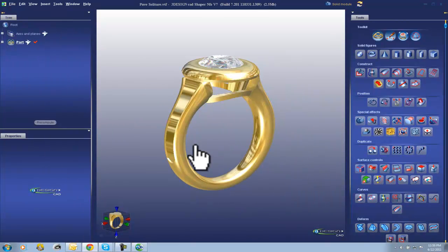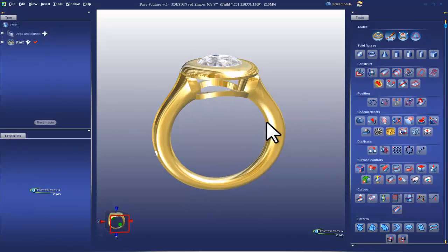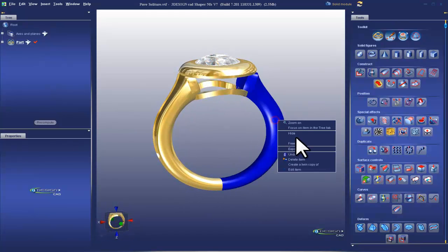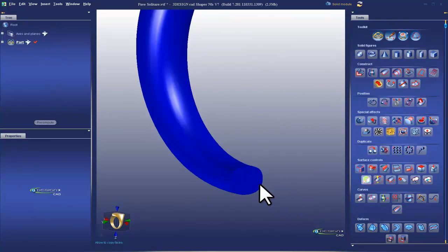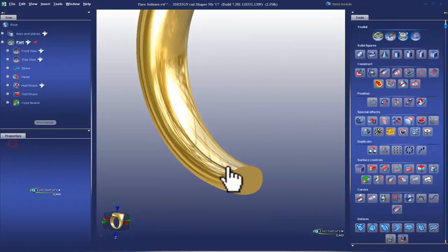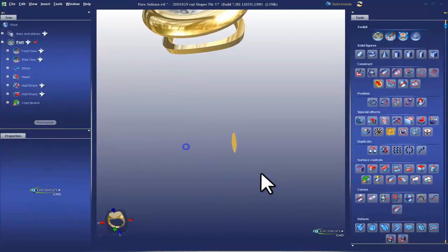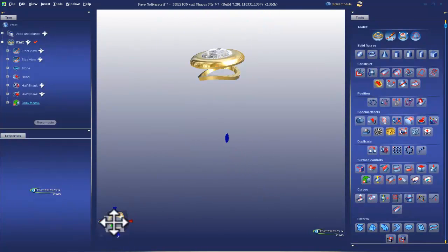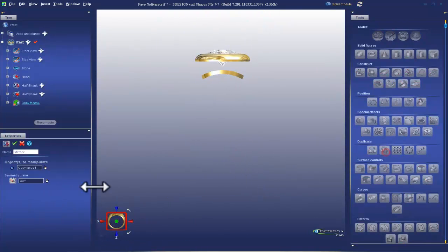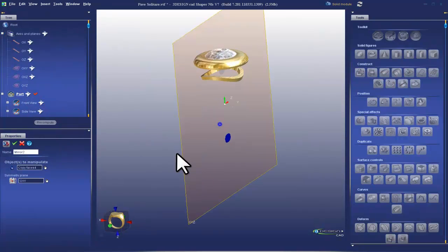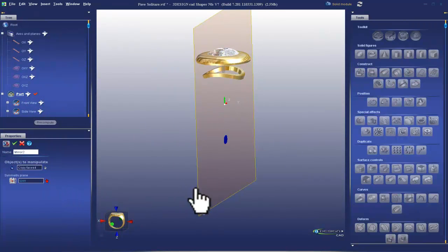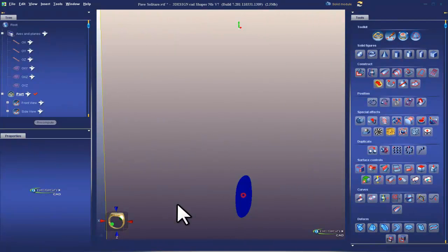Okay, so coplanar Boolean operations can be problematic. What is a coplanar Boolean operation? Okay, so let's copy this face here. That is a plane, let's say. Now, if I was to mirror this, because it's on 0, if I was to mirror it across the center plane, those surfaces are going to be directly on top of each other.